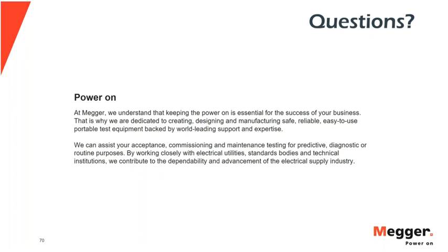But even so, you don't want a lot of losses in that insulation system, because that's in turn going to advance its rate of deterioration and degradation towards a place where it's not going to do the job it was intended to anymore. So yeah, those types of things are what I mean by electrical insulation health.